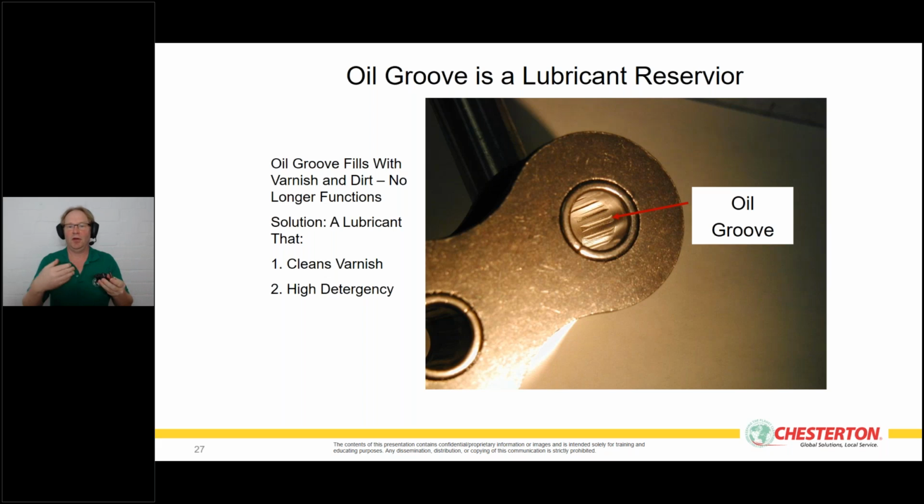And actually, in the grooves, the old oil reservoir is now a sticky material. So it means a good chain lubricant always needs to be able to wash that sticky material out. It needs to have very high detergency. Okay?